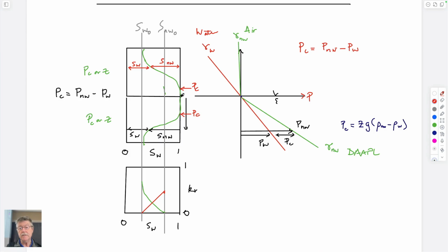100% saturated when it's at the water table, capillary tension saturated zone, so this is in tension, enough tension to keep it completely saturated, essentially, and then how these change. So this is air water, and this is NAPL water, and specifically DNAPL, right? Because it's below the groundwater table. And so we'll talk about these things today for NAPLs.